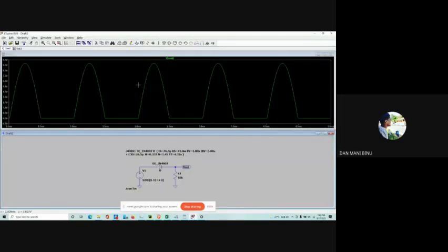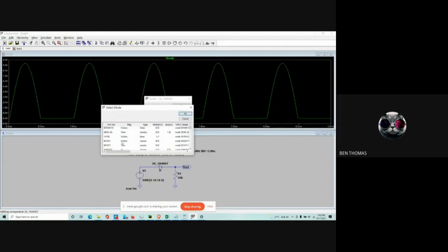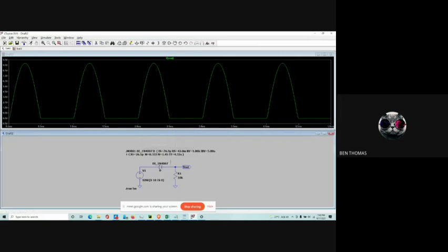Okay. And after that, if you have done this and saved this, still it won't work, you just have to close your draft and restart LTSpice for the changes to take effect. If I pick a new diode, I still can't see it because I haven't restarted my LTSpice. That's a difficult procedure, that's why I didn't want to explain it today. Okay, it's okay.